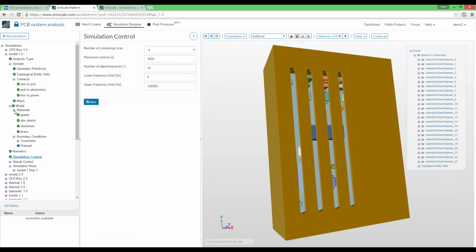For modal, there is a very interesting question. Could I recommend the number of cores to use? Do more cores allow us to get the results faster, or does it cost more? Obviously, there is a limit on the amount of core hours that you have. Every user has 3,000 core hours available at his disposal for the time being. Of course, if you go close to the limit, you can just contact us and we'll see what we can do. But obviously, getting more cores will increase your burn rate. Every real life hour of running on 4 computational cores will burn 4 times more computational power. At the same time, you get the speed up of the simulation.